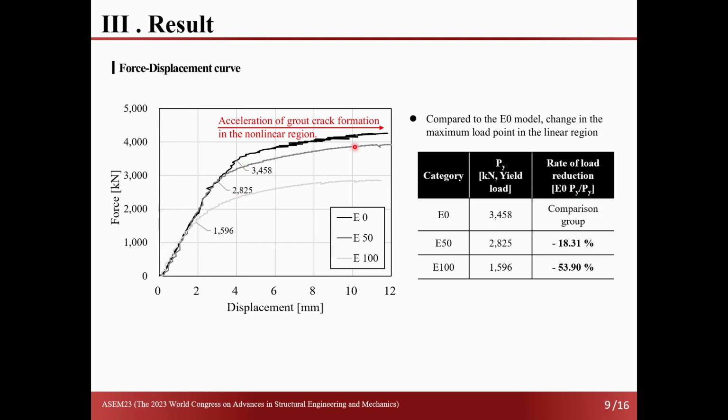In the nonlinear range, the degradation of the grout accelerates. Furthermore, the yield loads were measured as follows. In comparison to the E0 model, the E50 model experienced a decrease of 18.31% in yield load, while the E100 model exhibits a significant reduction of 53.80%.